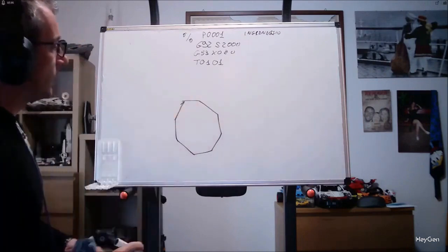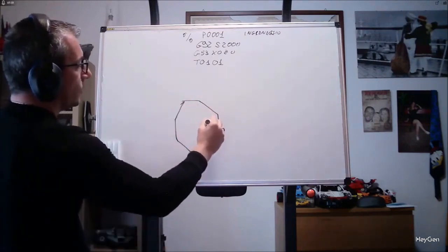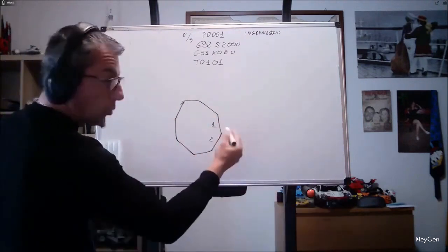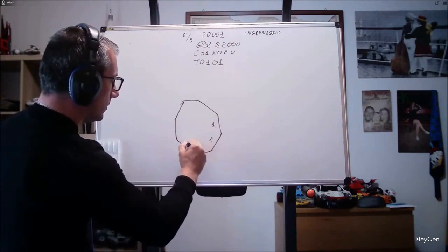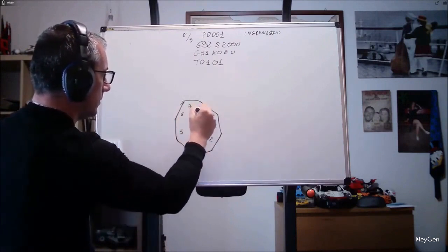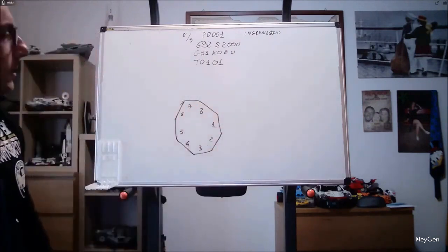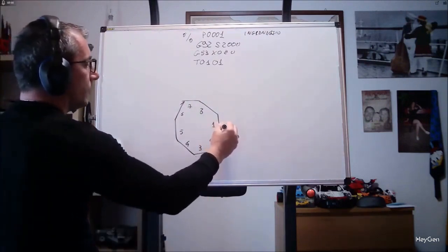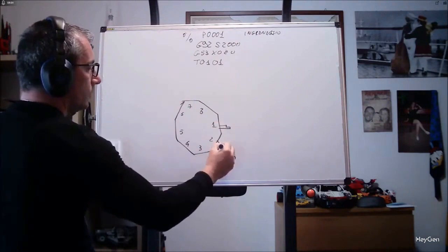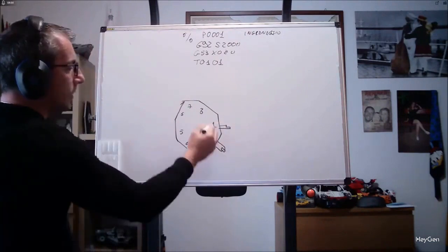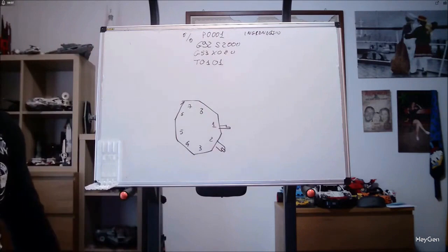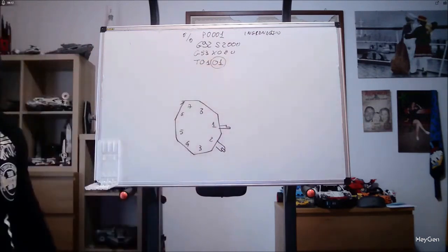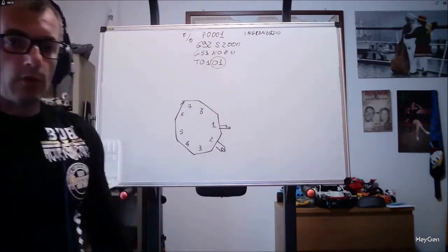You will have understood that I am not a great designer without CNC. It is made of 8 positions, 10, 12, 16, depending on the lathe you work with. You will mount a series of tools on these positions. So if you need a tool for grooving, rather than a tool for external turning, you will call T1 or T2, 01 or 02, meaning the offset, for this little number here. We will talk more about the offset later, just so you know.